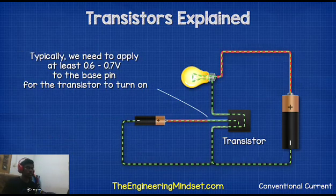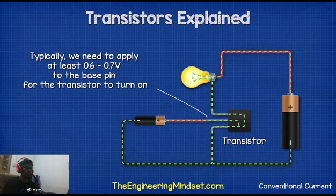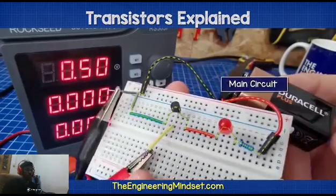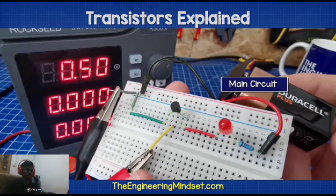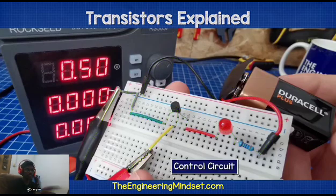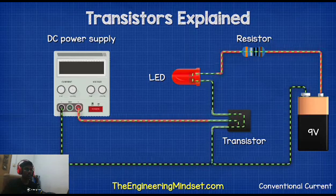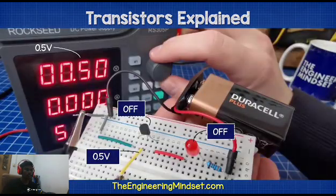Typically we need to apply at least 0.6 or 0.7 volts. At a voltage of 0.5, the LED is off. The main circuit is the battery, and the control circuit is here. The DC power supply is at 0.5, so the transistor is off and the LED is also off.